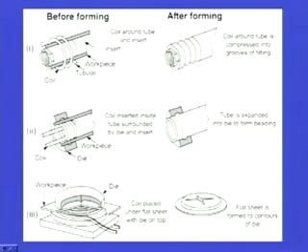Then there is a second case. Here the coil is inside the workpiece, whereas in the first case the coil was outside the workpiece. Here is the workpiece, the solid portion, and inside is the coil, and this is the die, in order to give the outer geometrical feature to the product that we want to make. So, the coil is inserted inside the tube, surrounded by the die and insert.